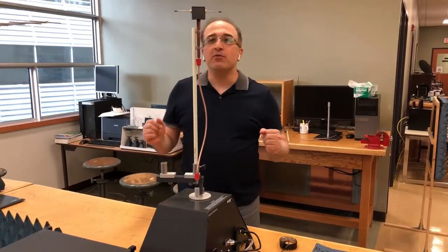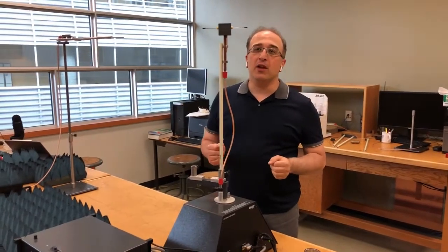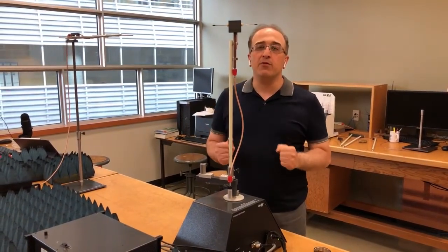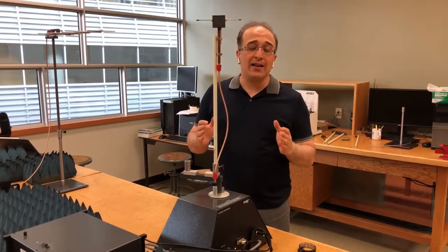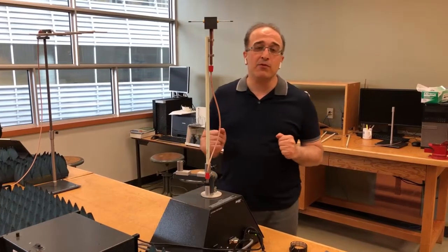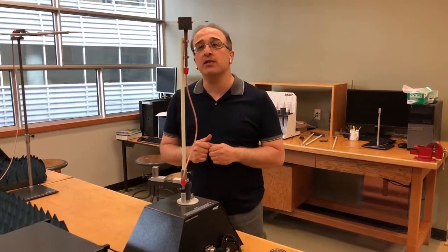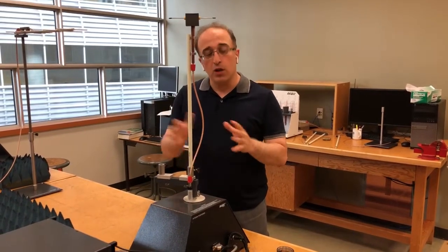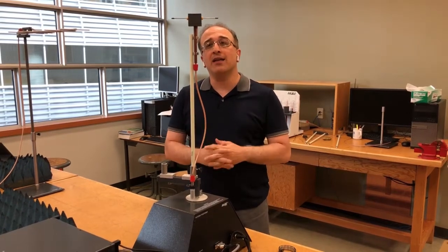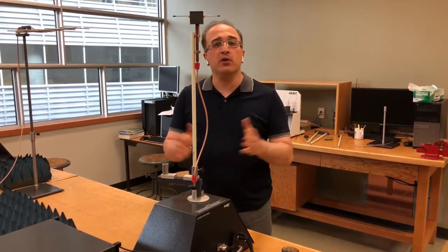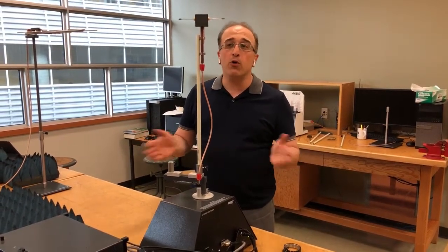In this experiment, we want to check what's going to happen if we decrease the length of the dipole antenna. So this is right now a half a wavelength dipole antenna. As you already know, this is not exactly half a wavelength, it's slightly less than half a wavelength so that the reactance goes to 0. If it's exactly at half a wavelength, we're going to have some reactance. So to make the reactance very small, we usually operate at a little bit smaller than half a wavelength, for example, 0.48 lambda or 0.45 lambda.